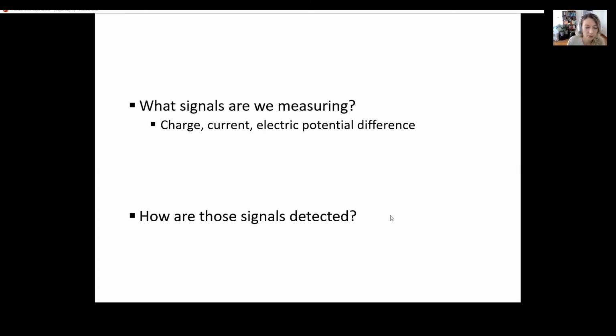The answers that we're looking for are more in terms of concepts like capacitors and voltage dividers. Really, that is the answer to almost any question during the course: voltage dividers. And the concept of an equivalent circuit. In equivalent circuits, we abstract away a lot of the system, and we really talk about, from the perspective of the charge, what is the charge experiencing? Things like resistance and capacitance are important to the charge. The charge doesn't really care about the brand of acquisition system. So we take all of that away, and we make it as simple as possible.